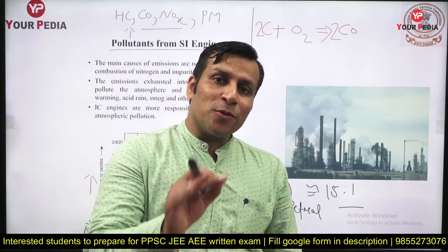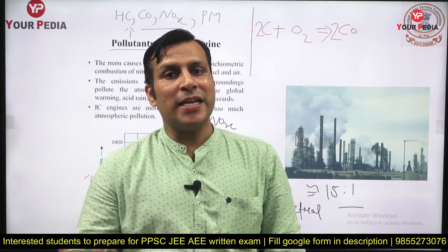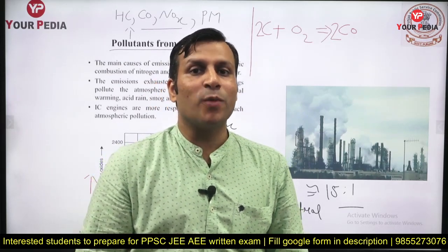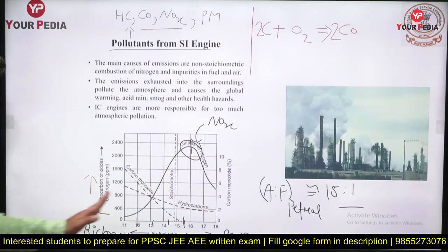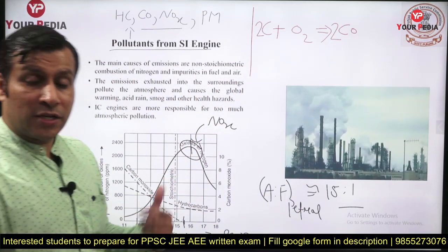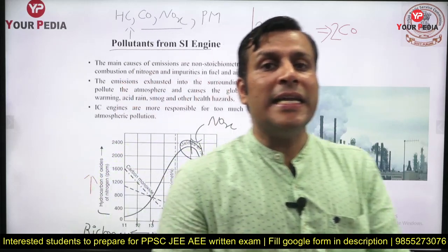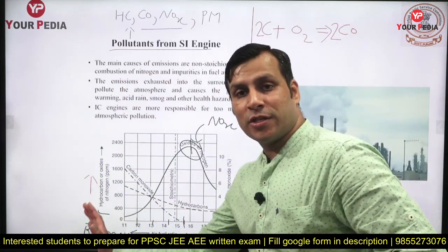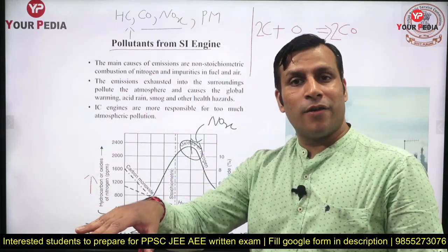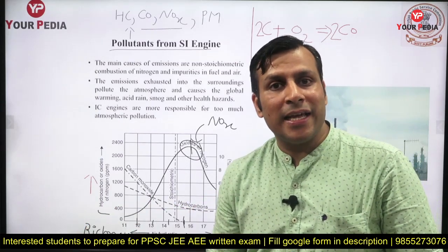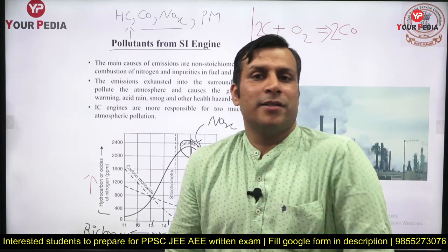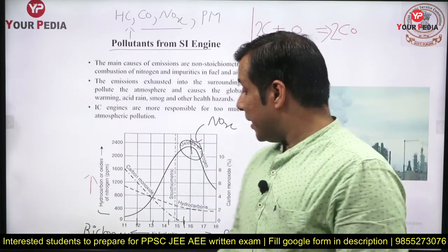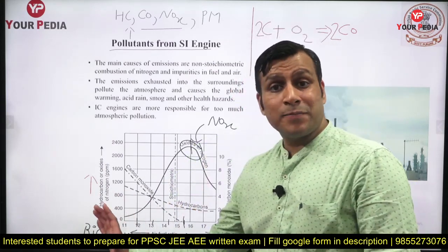So when that nitrogen is going to react with the oxygen, when there will be oxygen inside the engine, when you are supplying it in excess. If you are supplying very little oxygen, that means you are supplying a rich mixture, which is rich in fuel and lean in air. That is known as a rich mixture. It will have very little oxygen, and if oxygen is lesser, there will be no nitrous oxide formation. So nitrous oxide formation will be lesser with the rich mixture.